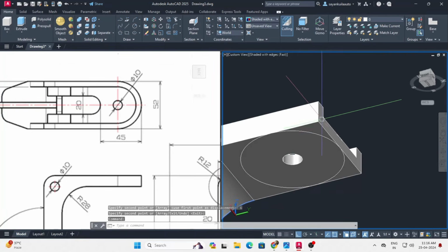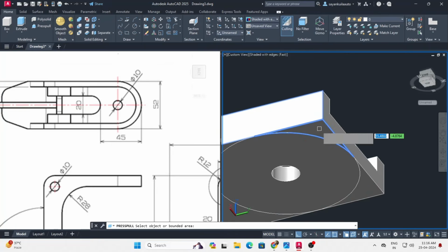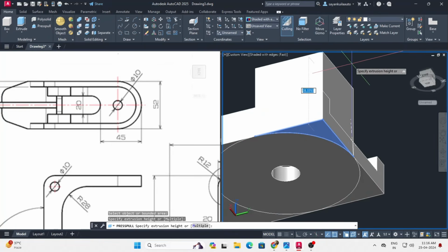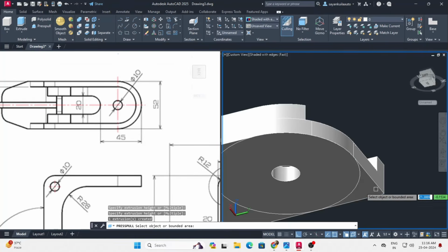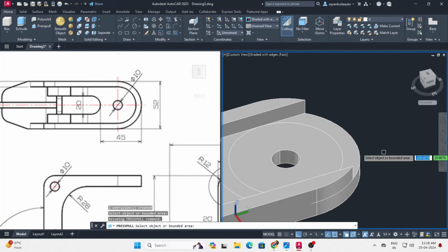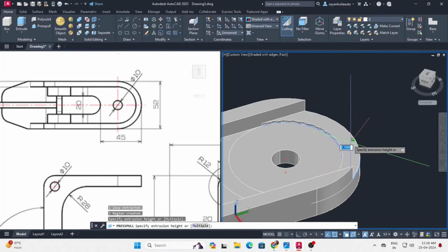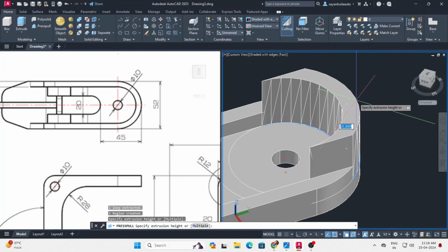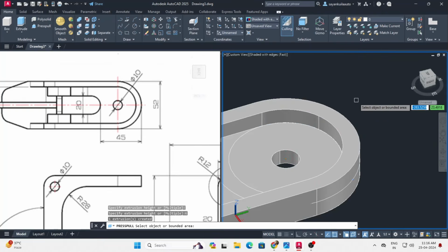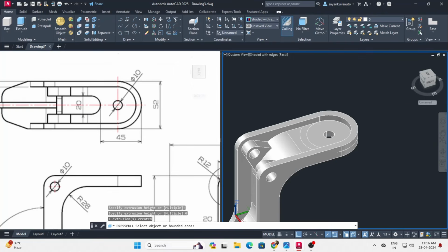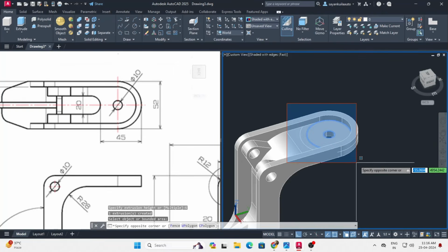I'll press pull cut this part. So click on press pull tool. Click at this part and then press pull it backwards like this. This side as well. And then I'll click at this part and press pull it upwards by 6 units. So this is done. I'll erase the 2D lines.